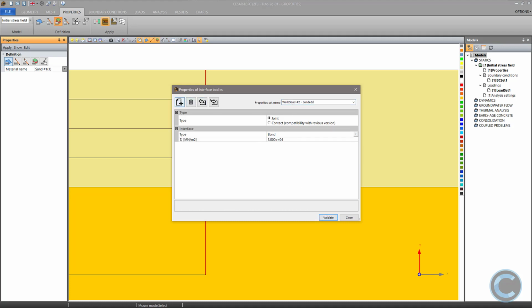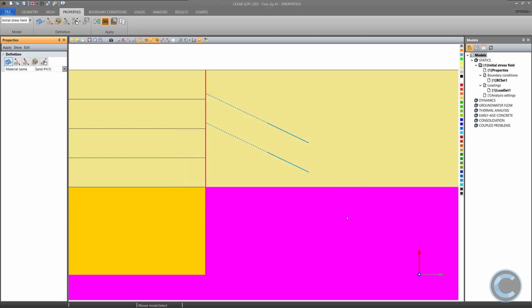When editing the properties of the column's friction behavior, E is a stiffness fixed to avoid numerical issues, the RT parameter is the tensile limit. It prevents the opening of the interface if the normal force is inferior to this value. The friction angle is valued at 2/3 of the soil one. Click Validate to save the data and close.